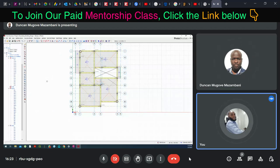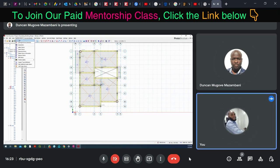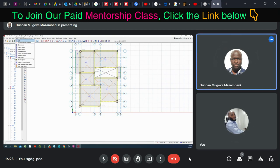Okay, to your plan view just now. Now to insert a story, click on the tab. You see Building Setup at the top there. Then you see Insert Story. Click there, Insert Story.